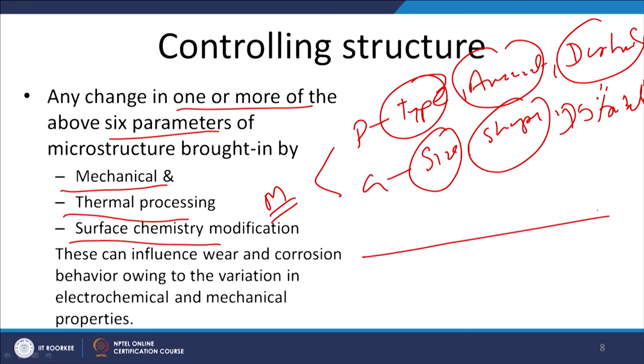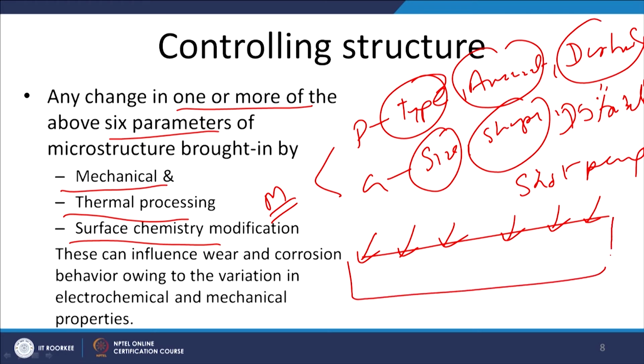Mechanical processing means the surface layer is subjected to localized stress application. It may be in the form of shot peening, burnishing, or contour rolling, so that the surface layers get deformed, work hardened and offer the required set of properties.